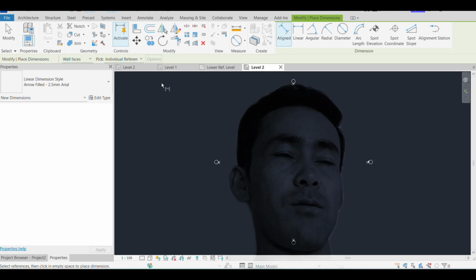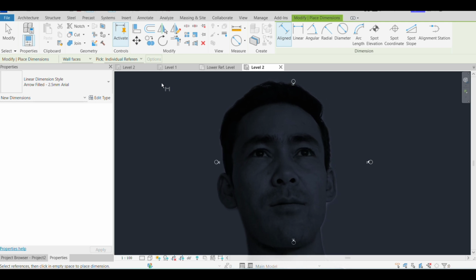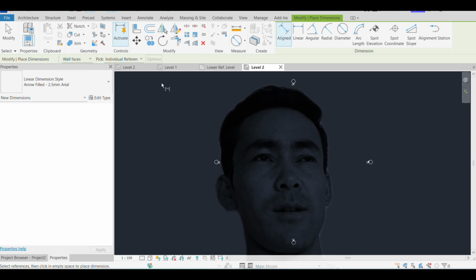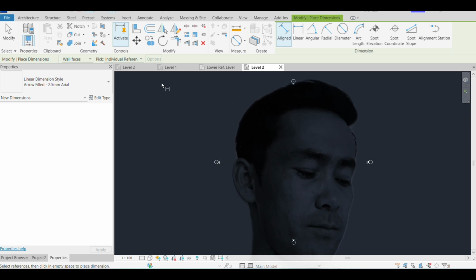And the duplicate views you can create independent and dependent views. The dependent views are used when there is a need to have multiple sections in a view. For example, if you have a large plan and the plan needs to be viewed with required scale, so you might need to have different views, and each view might be a dependent view of the main view.